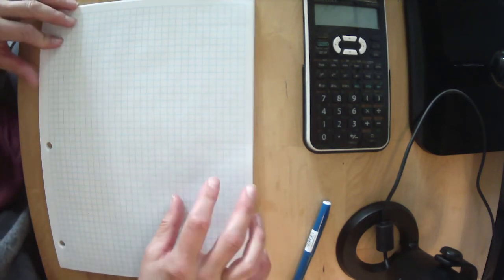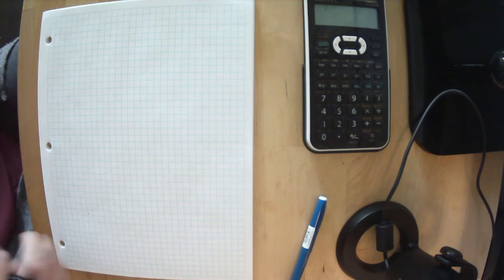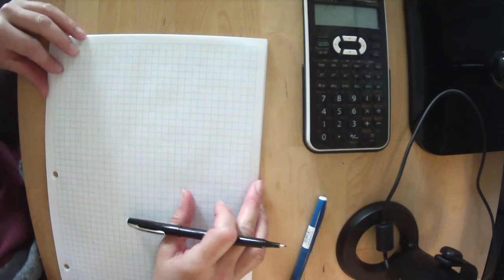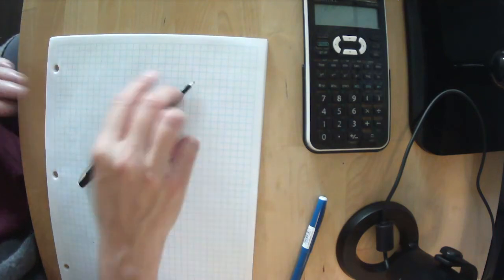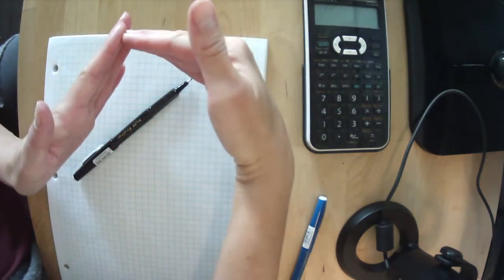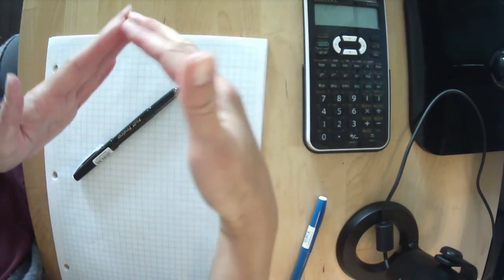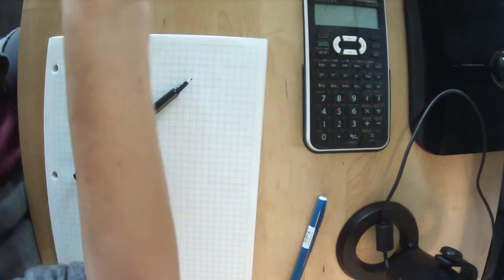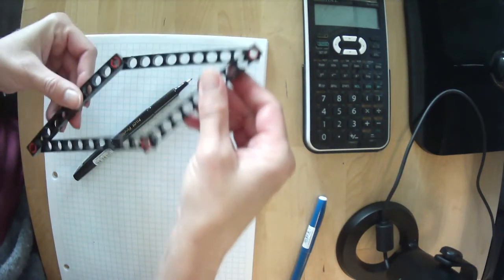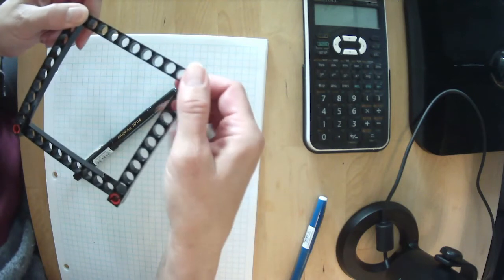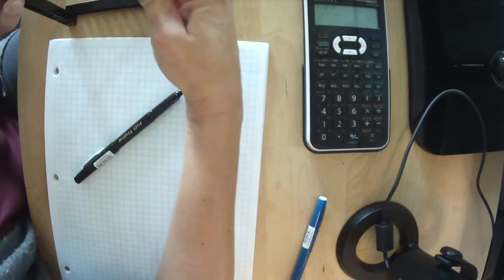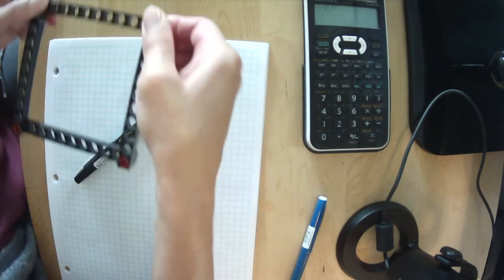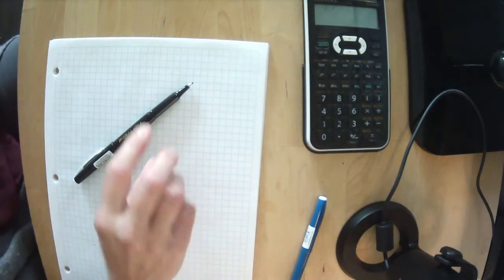Okay, so we have here our moment frame. Now remember, moment frame means that there's moment connections at the corner. So it's not like we have moment released. Instead of moment being released where it can swivel, we've got it locked in tight. Instead of this being able to do this, we're saying that these are glued together. And so for this to push over, it can't rotate here. These two points cannot rotate relative to each other. They're glued together. They have to stay at a right angle.